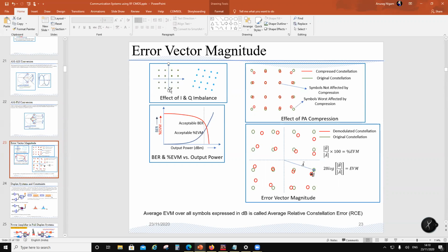So I can do frequency reuse and send I and Q on a single frequency. It's just that I use a sine wave and a cosine wave for modulating the two. That's the basic of a QAM system.